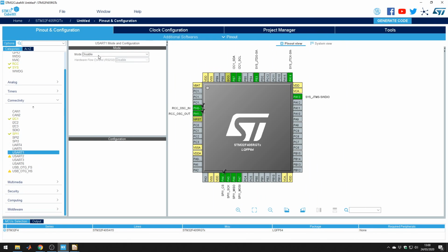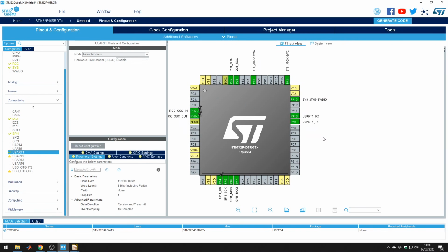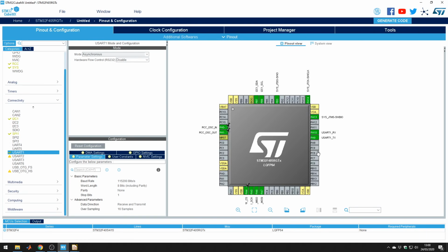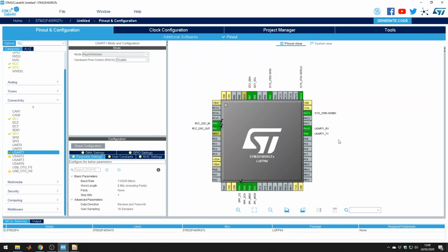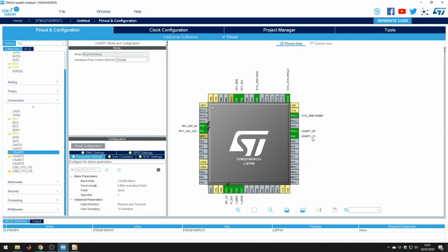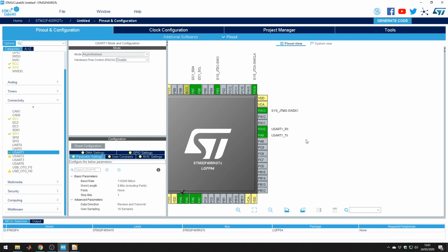Okay, what about a UART? Asynchronous, let's see where it puts it, PA9, PA10. Yep, so we've got TX and RX, and for now we can just stick with that. One thing I tend to do, because if you have a UART and you want to use UART for maybe debugging, for example, using printf to some sort of terminal console, you can do that, of course, via UART and then connecting to a UART to USB converter. And that's all fine, but that requires extra parts. You need an extra driver IC and so forth.